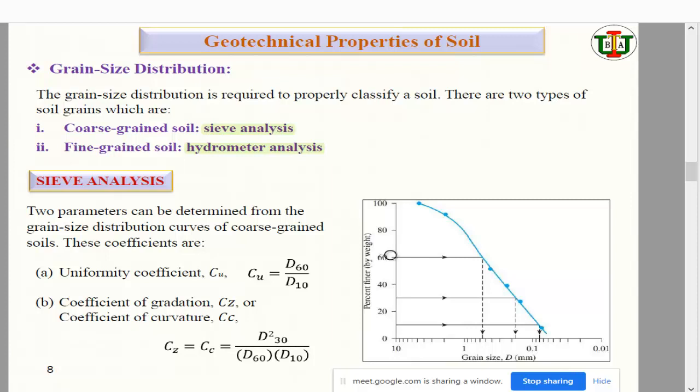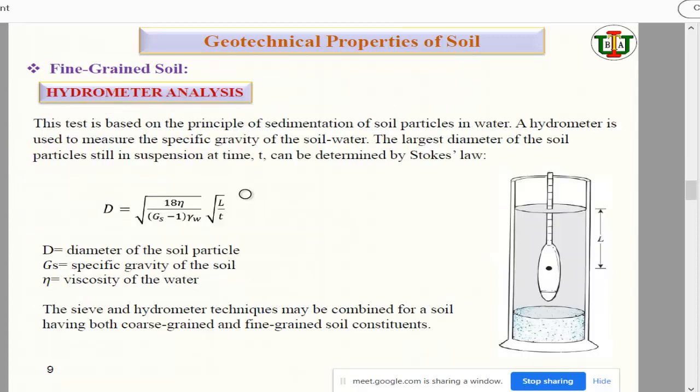So from the gradation curve we can see what the density expectations from the concrete could be. Similarly for soil, we can have a clear concept of how much denser the soil would be and how properly the grain size is distributed. So only the grain size distribution we can find out. I'm not going to discuss in detail how you did the sieve analysis, because this was part of your last semester study. I hope you understand, and you did the experiment also.